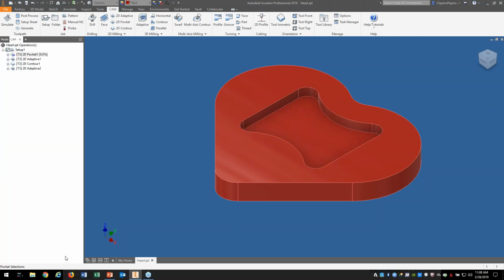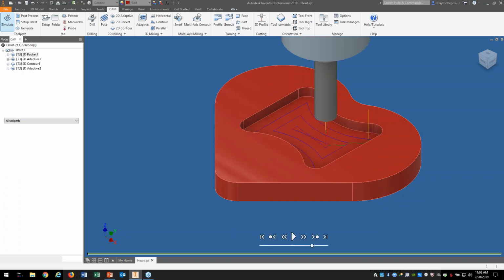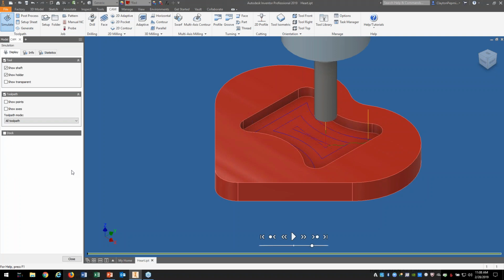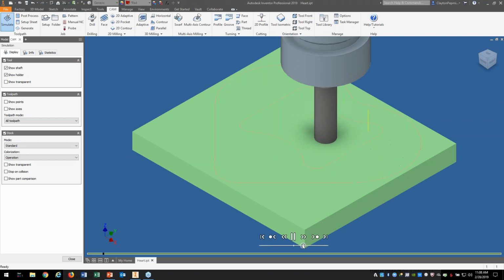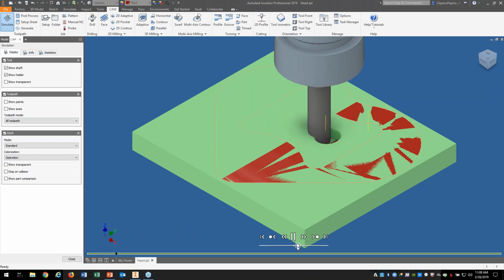So if I say okay to this, you can kind of see what the tool path looks like. I'm going to do a quick simulate on it because I want to talk about what you might run into cutting a pocket similar to this one. Now, as I go into this, hit simulate, you'll see I'm just doing a plunge entry and it starts cutting. Now, you might notice this section of the path right here. Even though I told it don't cut any more than 1/4 inch of tool or half of the tool, there's going to be parts in this where the tool is going to be 100% buried.